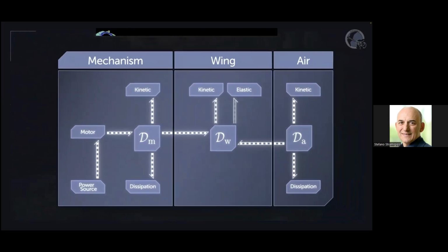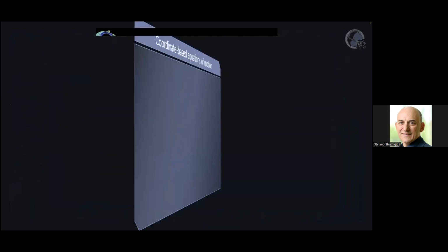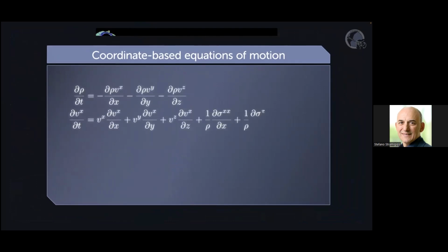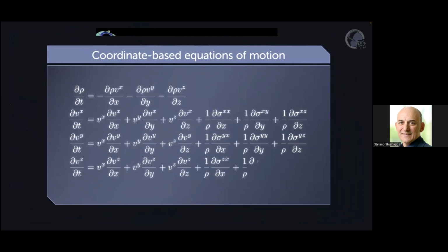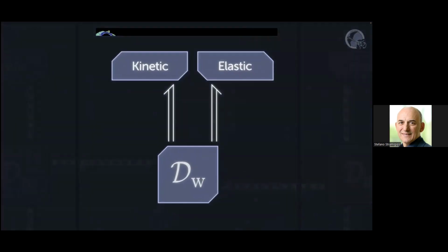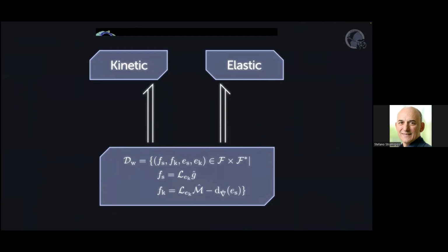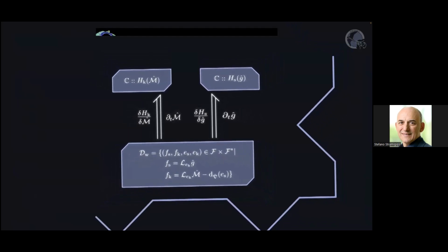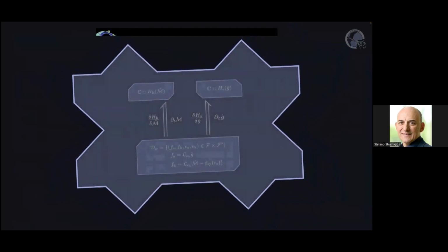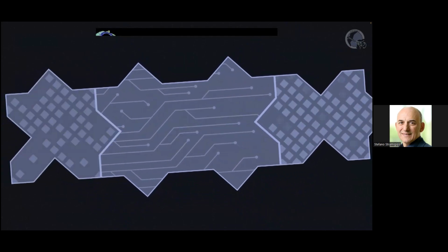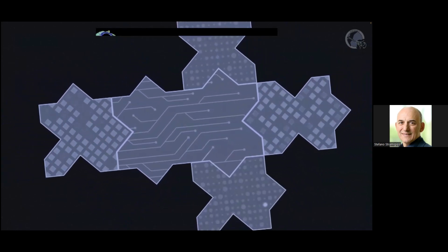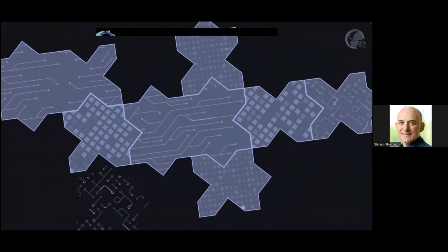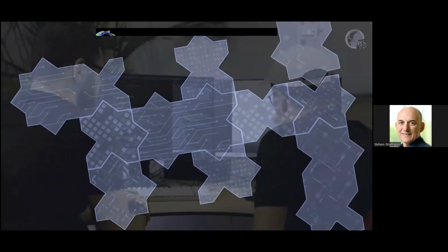Our Port-Hamiltonian description of this physical system differs significantly from the standard approach of continuum mechanics using coordinate-based tensor calculus treatments. We rely instead on coordinate-free exterior calculus and describe the network structure of the system using so-called Stokes-Dirac structures. This methodology allows us to intrinsically handle open boundary conditions and thus use, reuse and combine sub-models in such a way that a real Lego of physics would be possible.